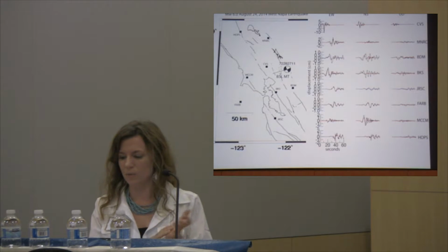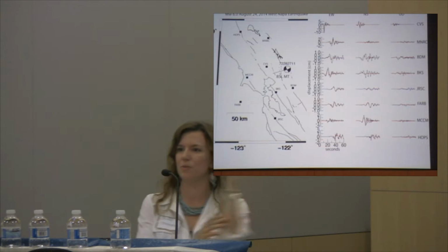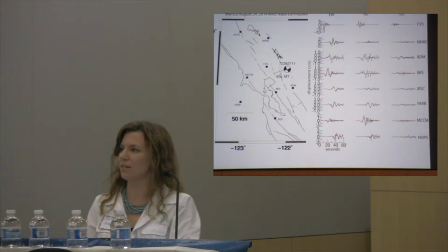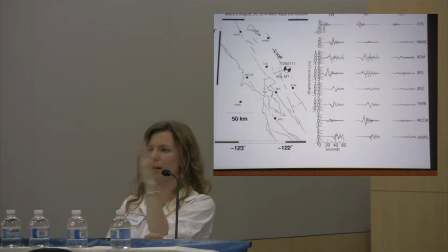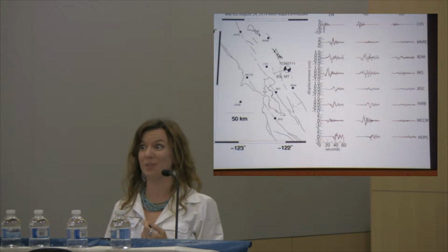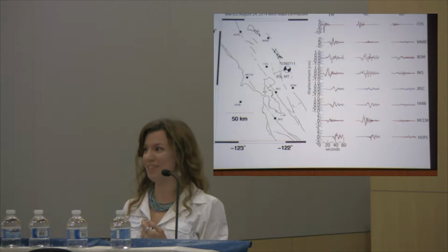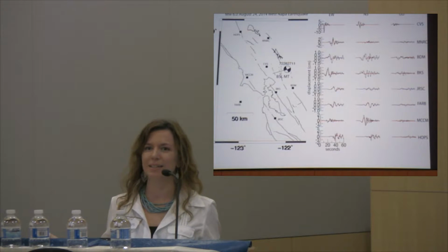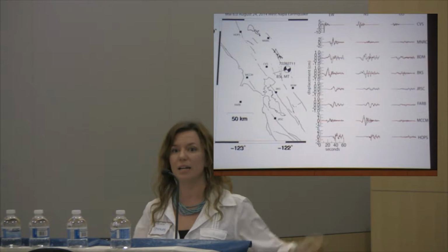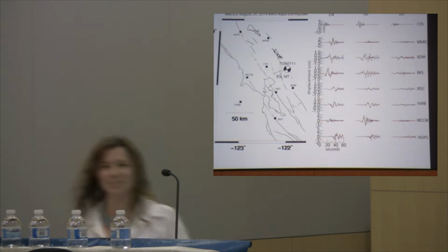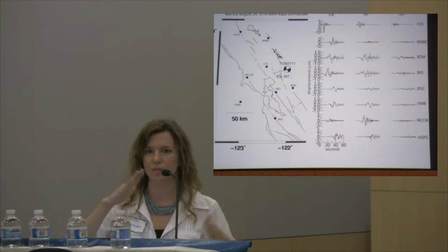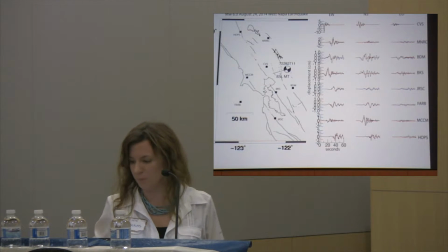Okay, so we talked about inverted pendulums. If you move the earth from side to side, the inverted pendulum is going to swing side to side. And if you damp it, it does a very good thing. Well, now we live in the modern age where we like to build skyscrapers, which are gigantic inverted pendulums, right? And so what's going to happen to gigantic buildings if you start moving the earth from side to side? Well, people on the 80th floor are going to go, right? Because no amount of steel bracing is going to help you in that realm.